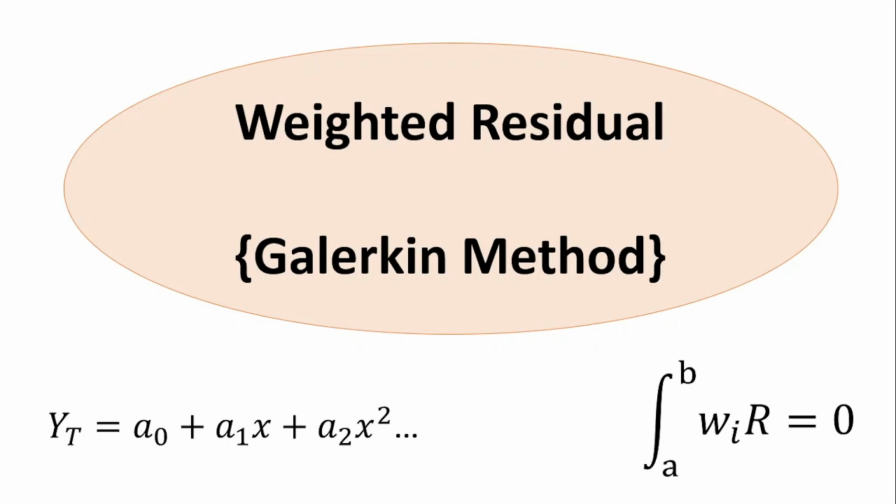There are really no restrictions to this, but there are certain conditions that guide your selection of a trial function. But we're not going into that in detail. It's when you're studying elements and their suitable trial function, or suitable interpolation function, that you begin to see that, oh yes, you are restricted. You cannot just truncate to make it too short an equation. There are limits to which you can do that.